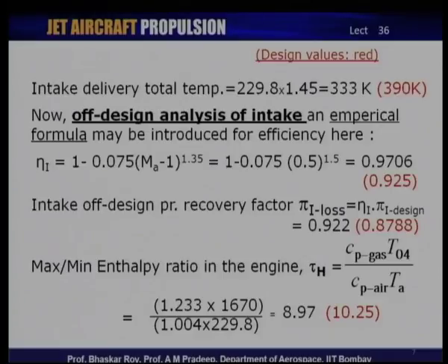Now, it stands to aerodynamic sense that the intake, once it has been designed, you would probably need to analyze it under various off design operating conditions. These off design operating conditions, at different ambient condition and different entry Mach number, would promote completely different kinds of aerodynamics inside the intake. In this case, we are looking at a supersonic intake, which means the shock structure in front of the intake would be quite different from the design shock structure, and as a result the flow through the intake would be quite different from the design shock flows, and hence the intake aerodynamics would be quite different.